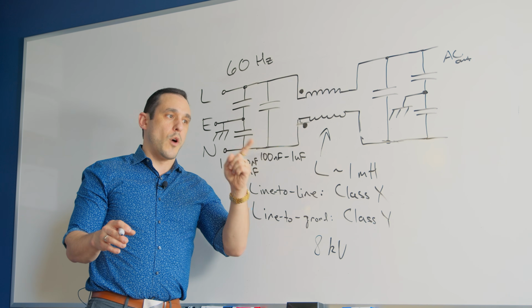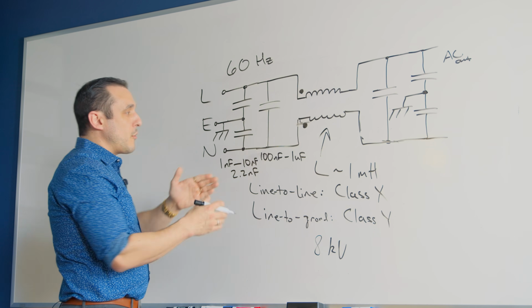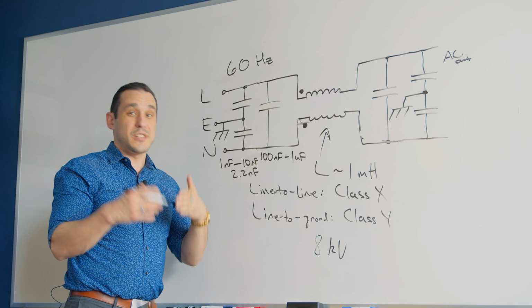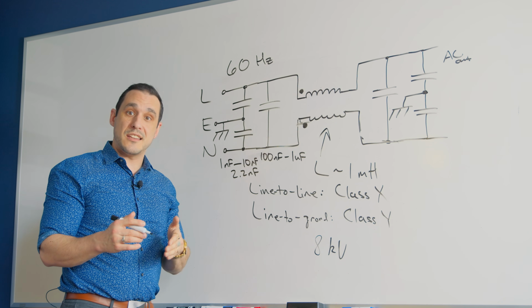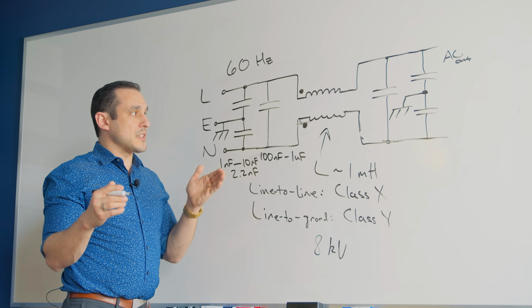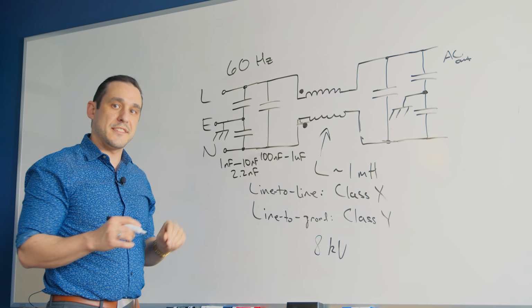In the case of our smart water pump controller design, we have an AC pass-through. So whether or not we need to use these components and the amount of current and voltage they need to withstand really depends on what that power is going to end up connecting to downstream. And in a lot of cases, it might make more sense to put this filter circuit on that downstream unit that this device is going to connect to.